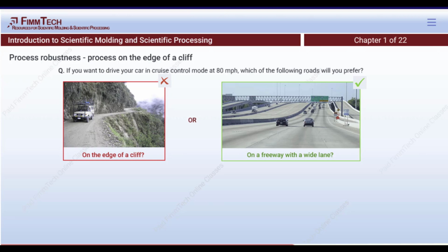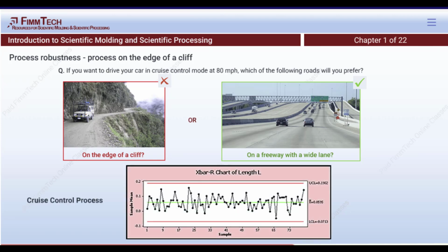My goal is to always have a molding process that runs in cruise control. That means once you set your process, it should run. We should not be tweaking it constantly, should not be changing processes constantly. It should not happen that the first shift has a different process than the second shift, and then the third shift has got his secret process down in the drawer. He takes it out and he's the only guy who can run this process. That should not happen. Those processes are not robust processes.